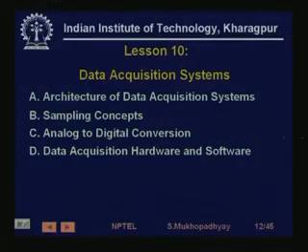So, one of the first things is to get these process level signals into the computer, and that is done through data acquisition systems. We took a look at the architecture of data acquisition systems, what they are made of and how they get the data into the computer. We started with sampling, then analog to digital conversion, and finally the interface with the computer and the software which lets a human being or a computer program see the data and analyze the data for control purposes.